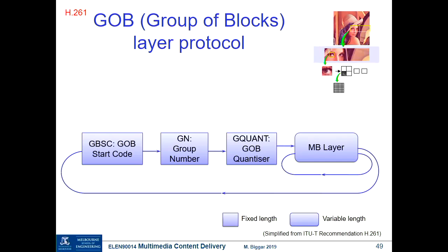Okay, well, we've gone late enough. So the idea is just that if this quantization step size is good enough, then it just saves having to define it for each macro block inside. So it just saves bits. But if it's not accurate enough, or we have enough bits available anyway, then we can redefine it inside, and that's the only idea behind that.